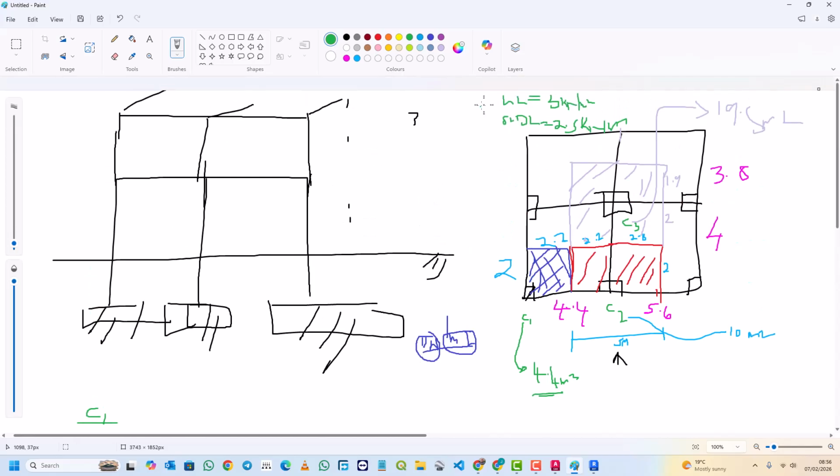So how do we convert this live load into a point load that is going to be supported by the column? It's very simple also. You just take your load, 3 kilonewton per meter squared, then you multiply by the area. I think you remember we said pressure is equal to force over area; this is physics form 2. So for you to get the force, it's also simple. You just cross multiply and you'll get pressure, which is this load, multiplied by the area.